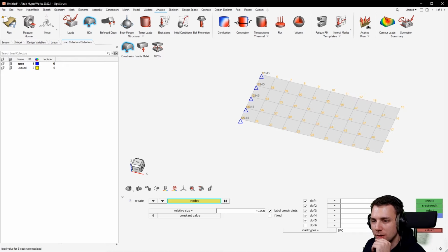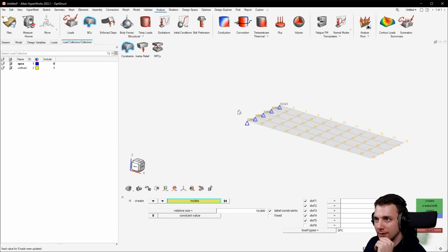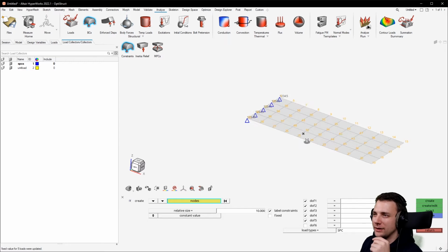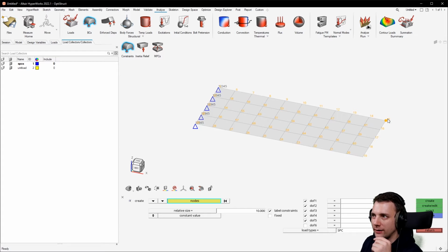And what we want to do now is to create the oscillating function, right? So we have now created the constraints where we hold this plate fixed, right? So we hold that in place. And then on the other side, we want to have an oscillating function which excites the plate here up and down, for example, at some point, right? So this is what we're doing next.